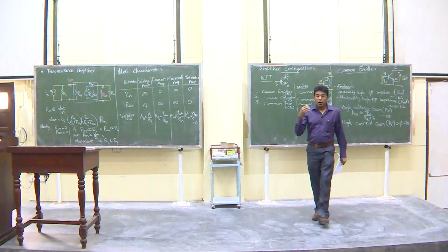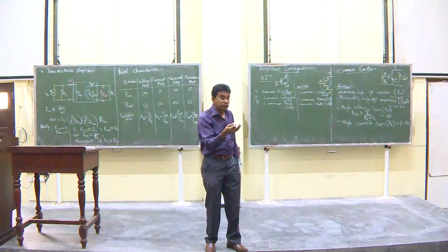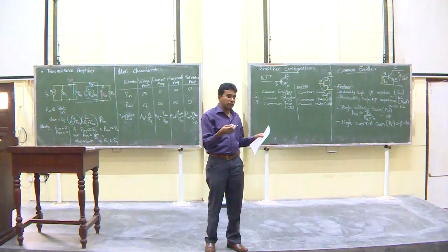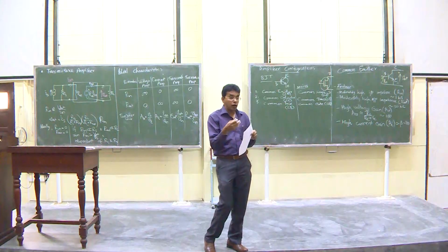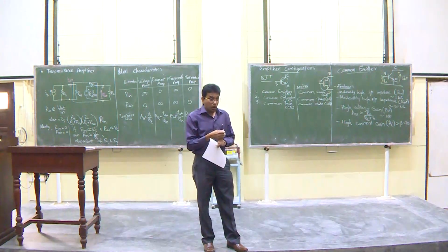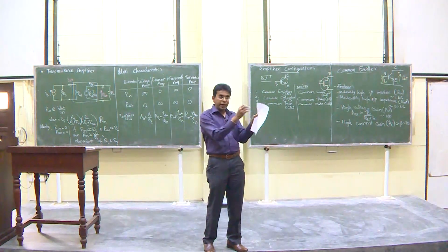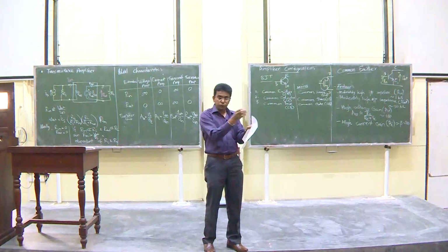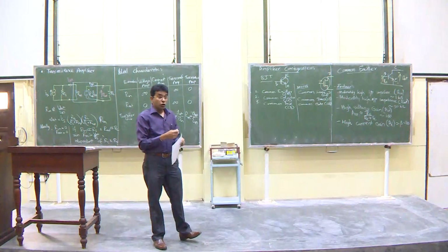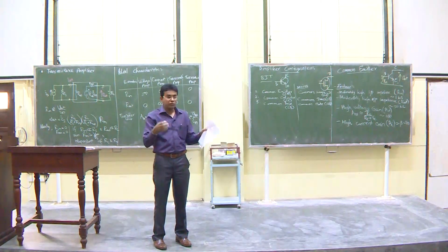Now, you see you have a very large current gain and a very large voltage gain. Output power is basically output voltage times output current, divided by input voltage times input current. So what you end up having is voltage gain times current gain times the input power. So that is really large. You gain really large power gains here.